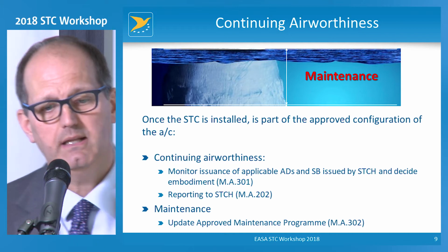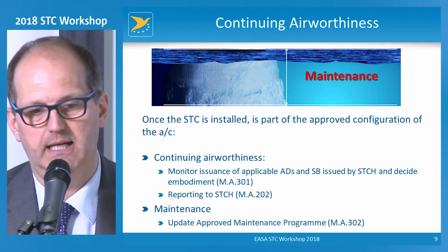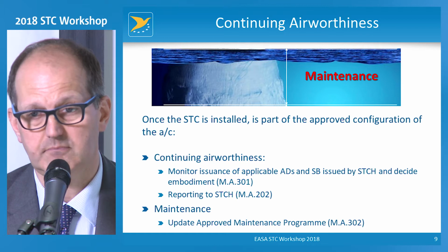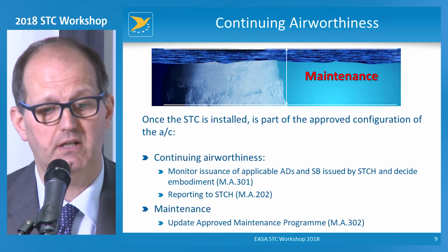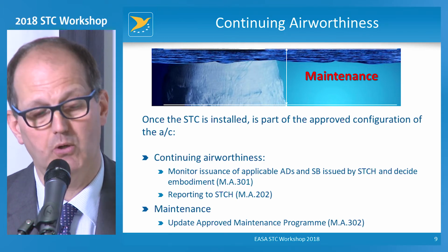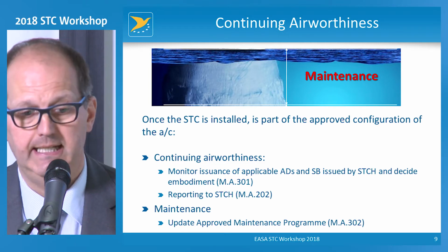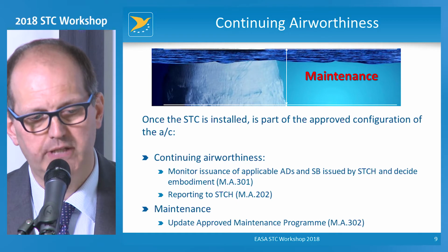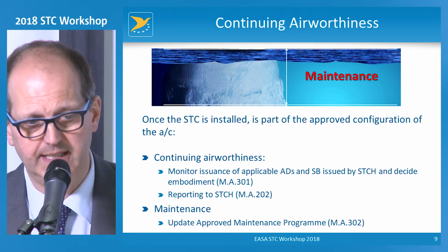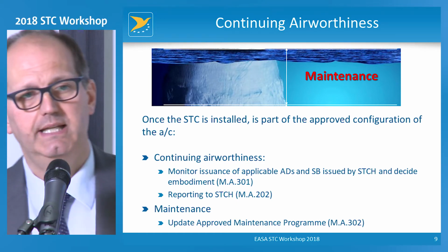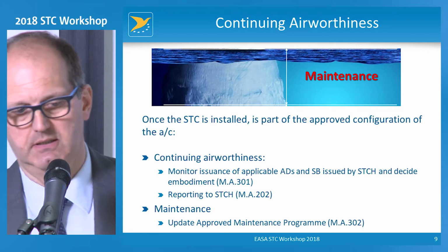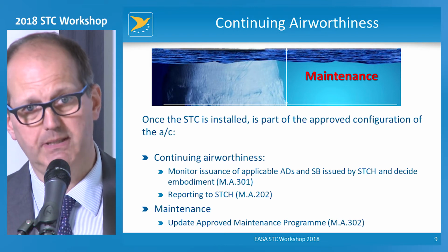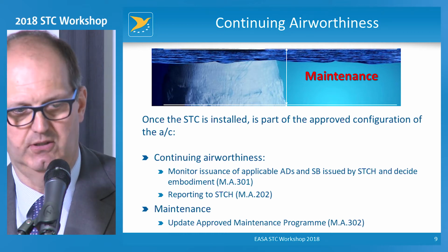Now, with the aircraft modified with our head-up display, the configuration of the aircraft that needs to be maintained, its airworthy configuration, is changed. And the continuing airworthiness of the aircraft is not only what is dictated by the manufacturer, by the TC holder, but also what is dictated by the STC holder.